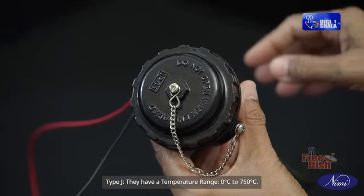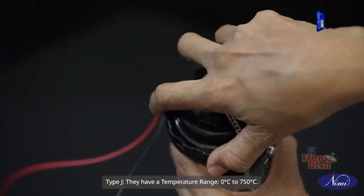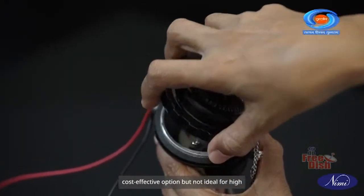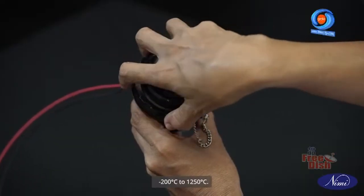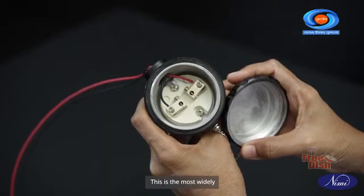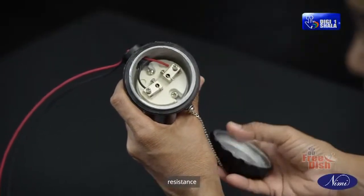Type J, they have a temperature range from 0 degrees Celsius to 750 degrees Celsius. This is a common and cost-effective option, but not ideal for high temperatures. Type K, temperature ranges from -200 degrees Celsius to 1250 degrees Celsius. This is the most widely used thermocouple due to its wide temperature range and good corrosion resistance.